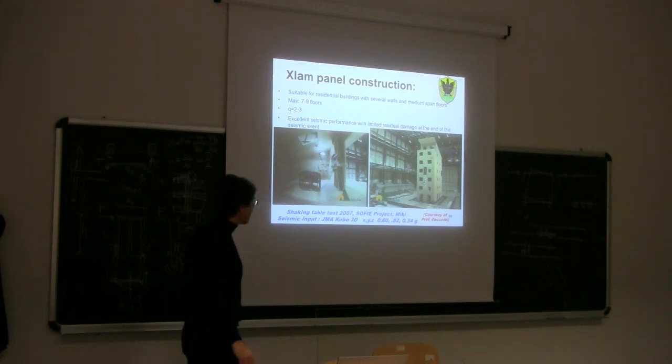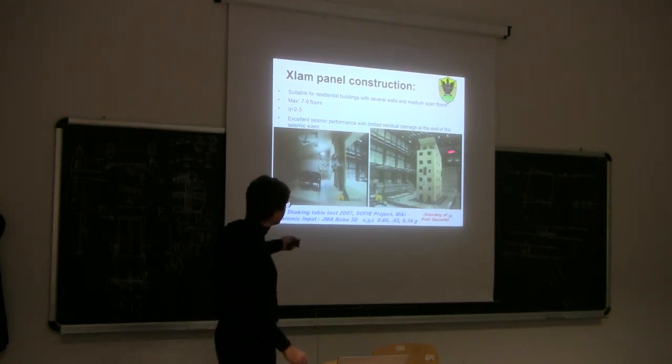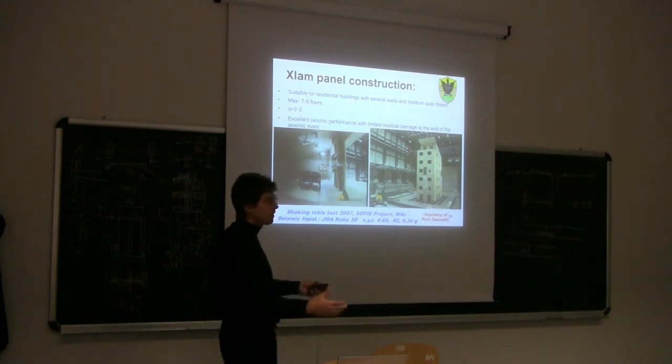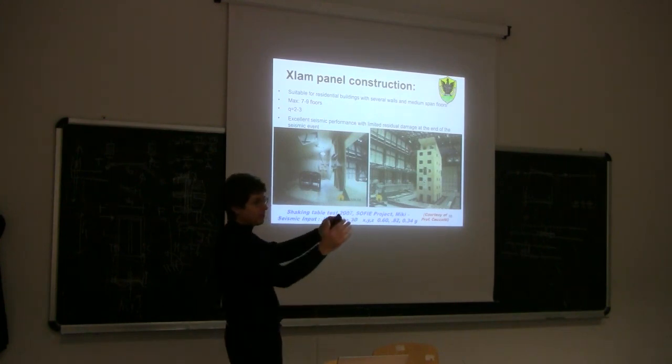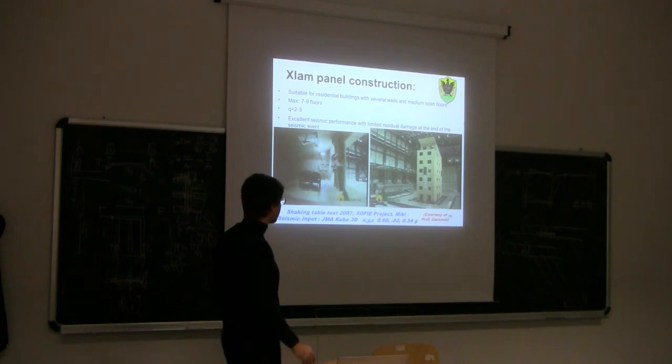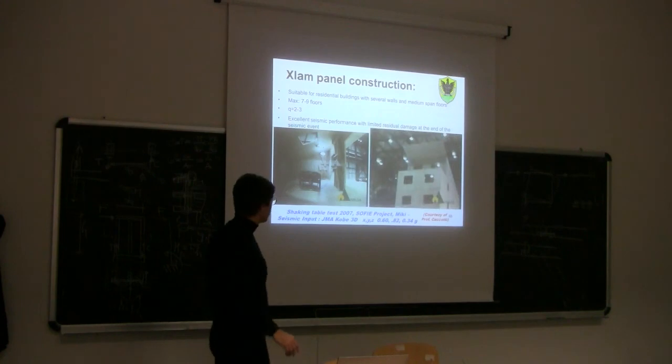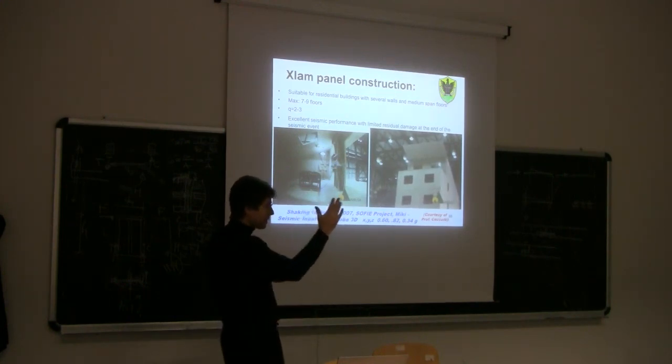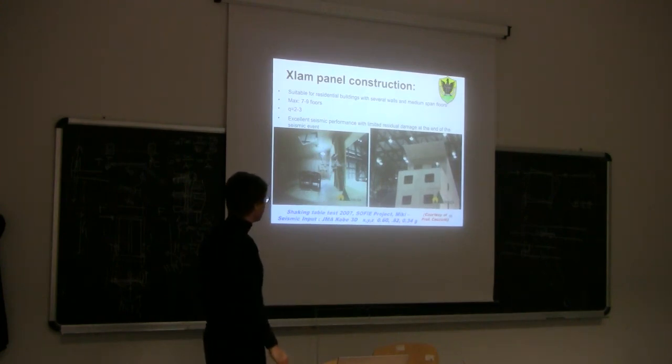And again, you can notice that there is quite a significant movement on top of the building, because again, timber has a problem of having a very low modulus of elasticity, meaning that we have very strong displacement, as you can see. Now we will concentrate just on the top. So quite flexible. Despite the fact that this is a rigid structure, it is still subjected to significant fluctuations due to the earthquake.